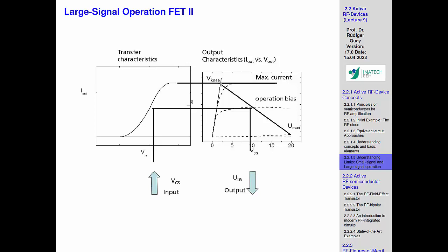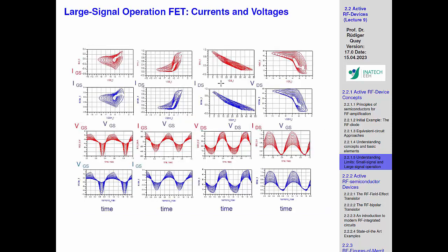And you see the dynamic swing here. So this is really the dynamic change. You see this is not going down to zero. There's a knee. The zero line is here. And it's reaching here a maximum of, so this is biased here at 25 volts, and you see it's going up to 50. So it's really symmetric around the 25 volts. So that makes a lot of sense.